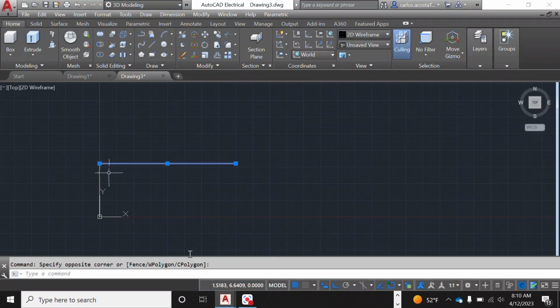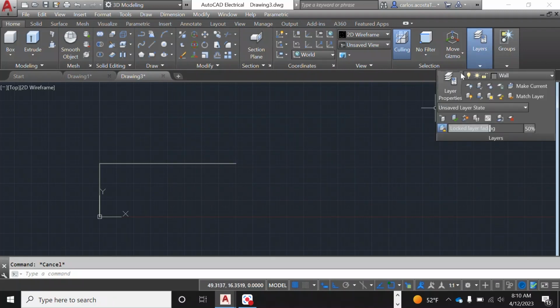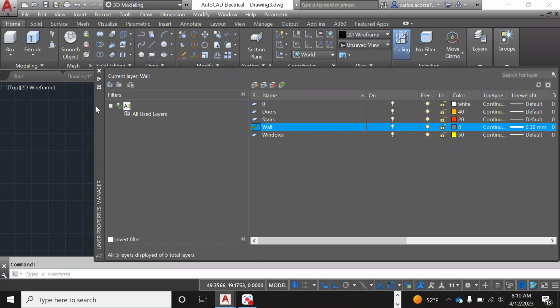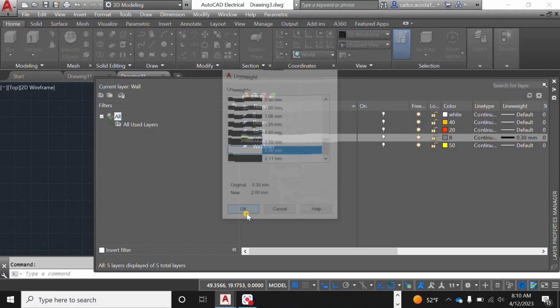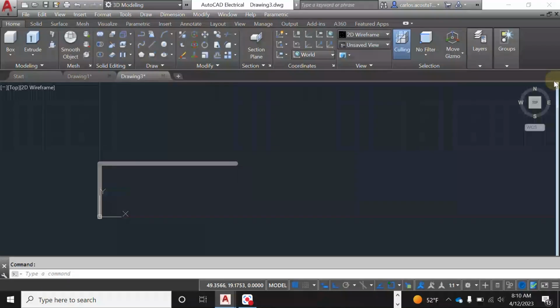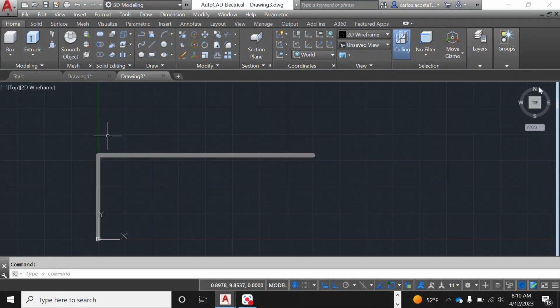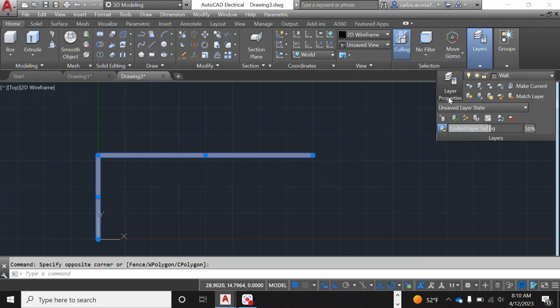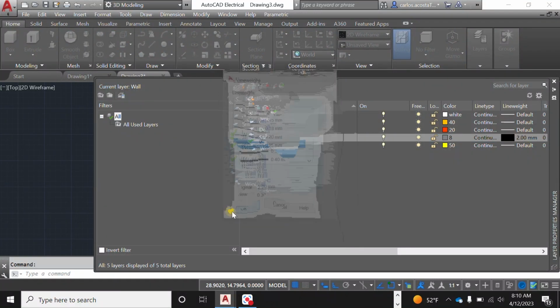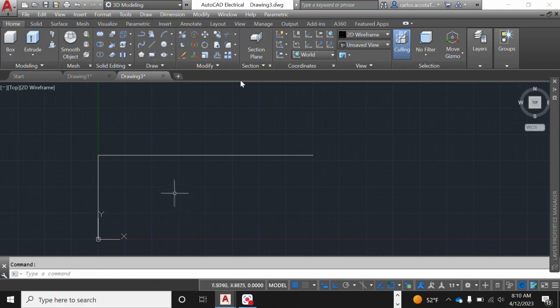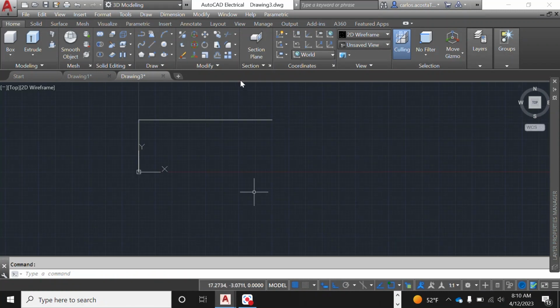And how do you know if that is changing the thickness of the whole layer? If you want to change the thickness of all the objects in the whole layer, you go to layer properties, and as you can see, it's changing the thickness. Okay, so let's keep something more realistic. Let's go to layer properties. Let's do 0.3 millimeters thick. And this scale is 1:1, so it's going to print 0.3 millimeters on your paper.